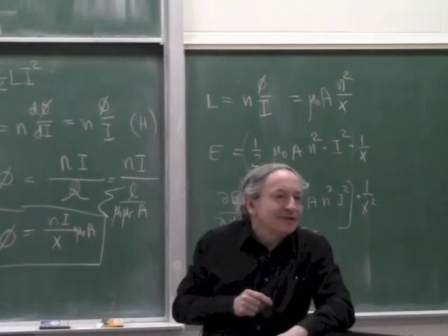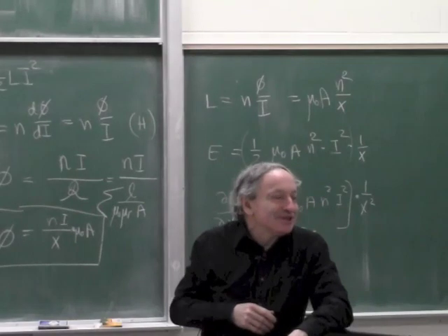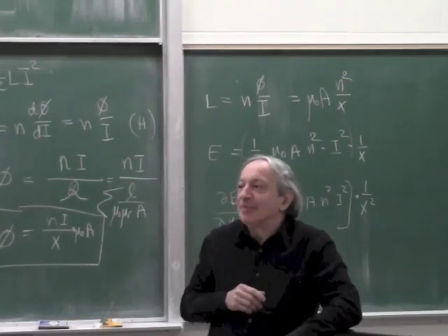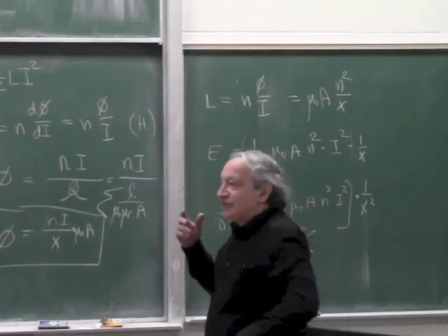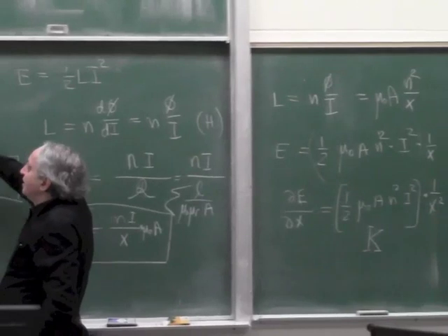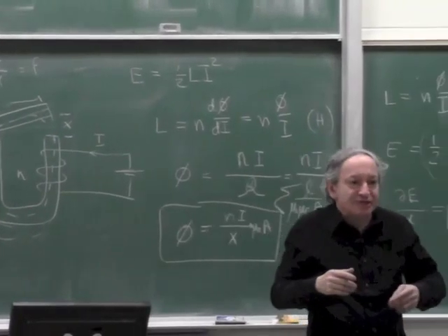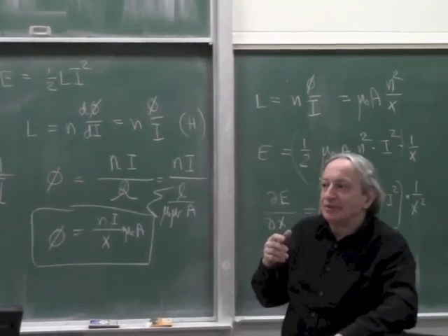More calculations. Okay, but computers today are cheap, they can do the calculations, but there is something fundamentally bad about something which is variable gain. If you think about it, if this is nonlinear with position, the gain of the whole loop changes, because as it gets closer, the gain goes up.